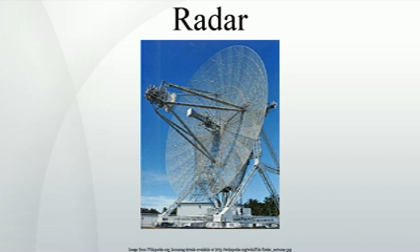These precautions do not completely eliminate reflection because of diffraction, especially at longer wavelengths. Half-wavelength long wires or strips of conducting material, such as chaff, are very reflective but do not direct the scattered energy back towards the source. The extent to which an object reflects or scatters radio waves is called its radar cross-section.